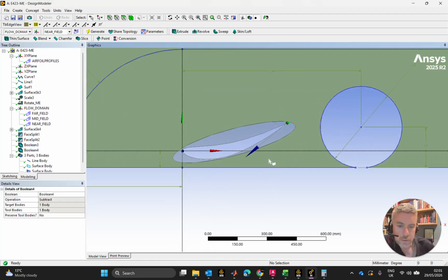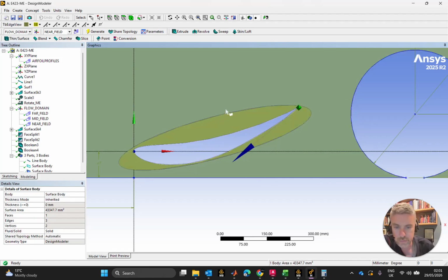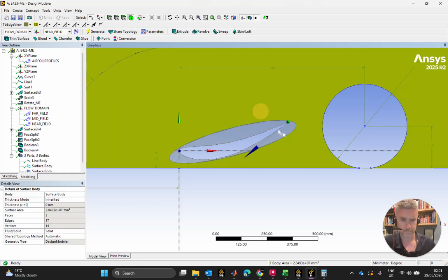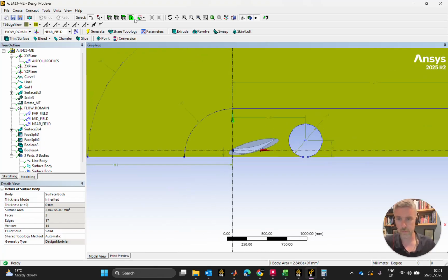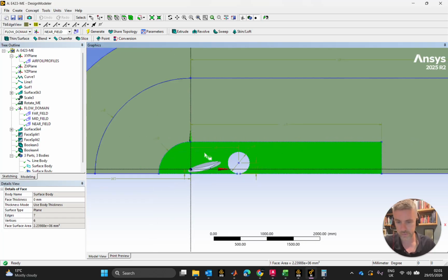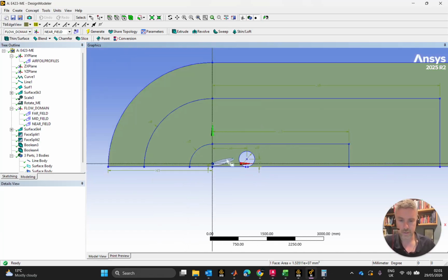Now, what I have here is an empty region where I have my solid airfoil, and an empty region where I have my solid wheel and tire. I have a region in here which is going to be my mesh protection zone for the airfoil, to stop any skewing or orthogonal problems whenever I alter my angles of attack. Out here I have near field meshing, so I can put that down to a very tight mesh, not as tight as what I'm going to put in there. A midfield out here, and then a far field out here.